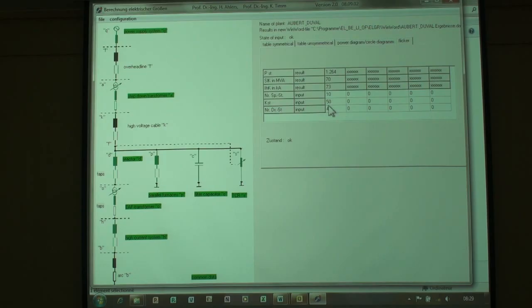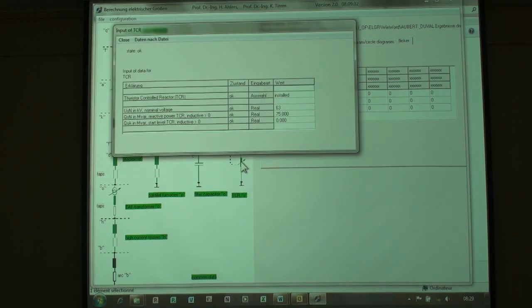50 is considered to be, let's say, the ladle furnace, for example, or foaming slag. And let's say a powerful furnace, start of melting, it's about 90. So with this, you know what kind of harmonic you can expect with this SVC.